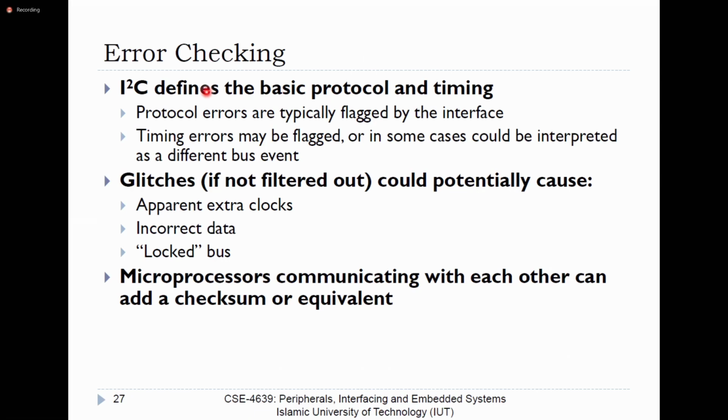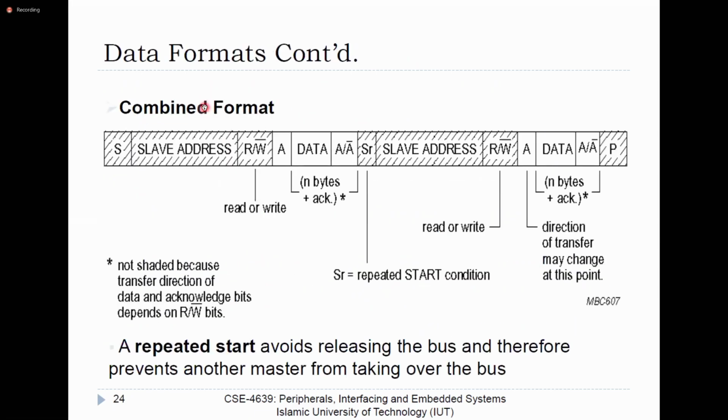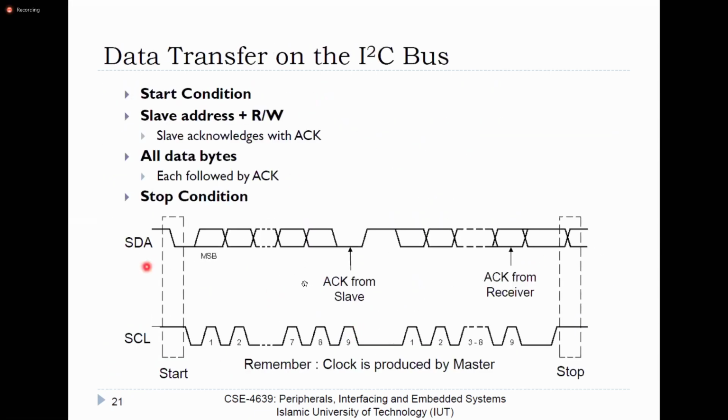The receiver also follows the clock pulse, and the data transition should be made when the clock pulse is in the low state. When we say that an error has occurred, that 1 becomes 0 or 0 becomes 1, if any data transition occurs when the clock pulse is not in the low state, the receiver will identify that an error has occurred.